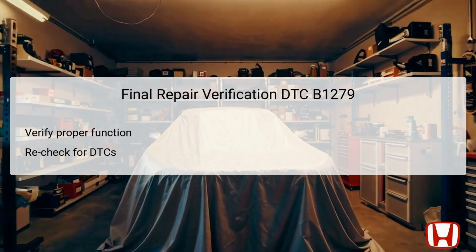After completing all necessary repairs, it is crucial to verify that the vehicle's lighting systems are functioning accurately before concluding the job. Run a final test on the dimmer switch and combination light switch to ensure they respond properly across all settings. Once you confirm that the dashboard lighting and headlight functions operate as intended, you should again check for DTCs using the HDS.